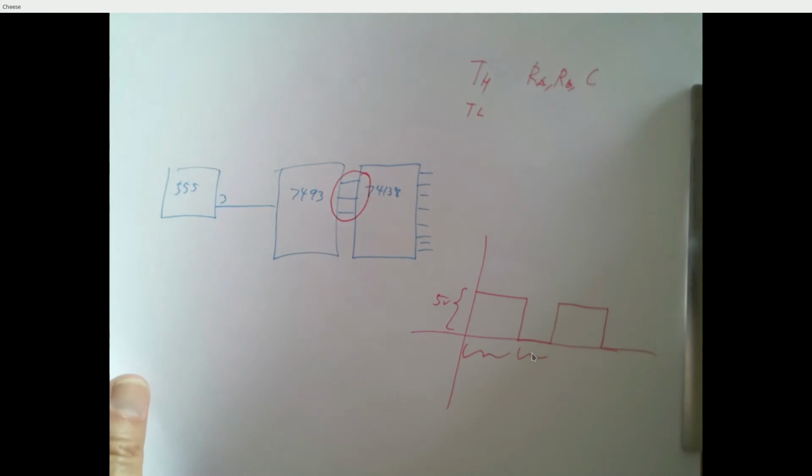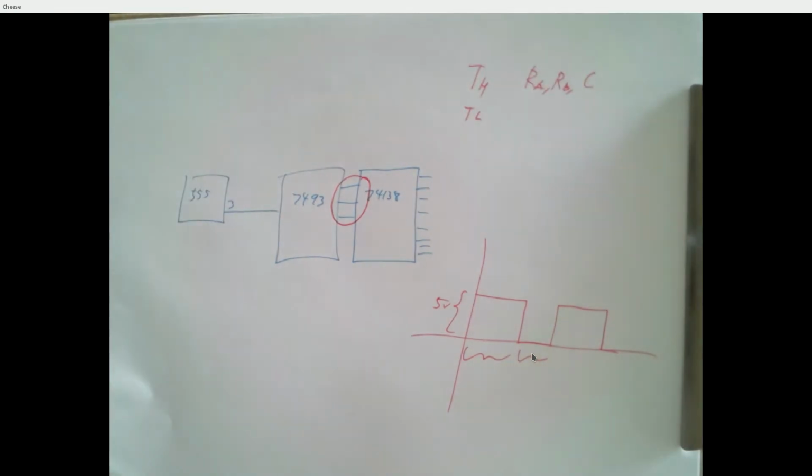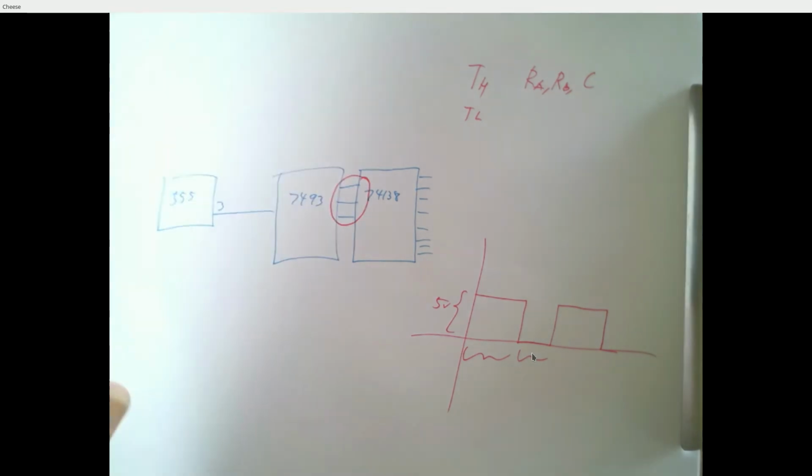So the adder experiment, for example, right? We saw the truth table for the full 2-bit adder, right? Before we talk about half adder, full adder, we made a truth table for 4 incoming bits and 3 sum bits coming out. And we said there's 16 rows and there's 3 outputs, right? And then in the lab, you were supposed to write an equation based on that truth table for each of the outputs. Look at how many terms there are, the literal count, and then switch gears and do this half adder, full adder design.